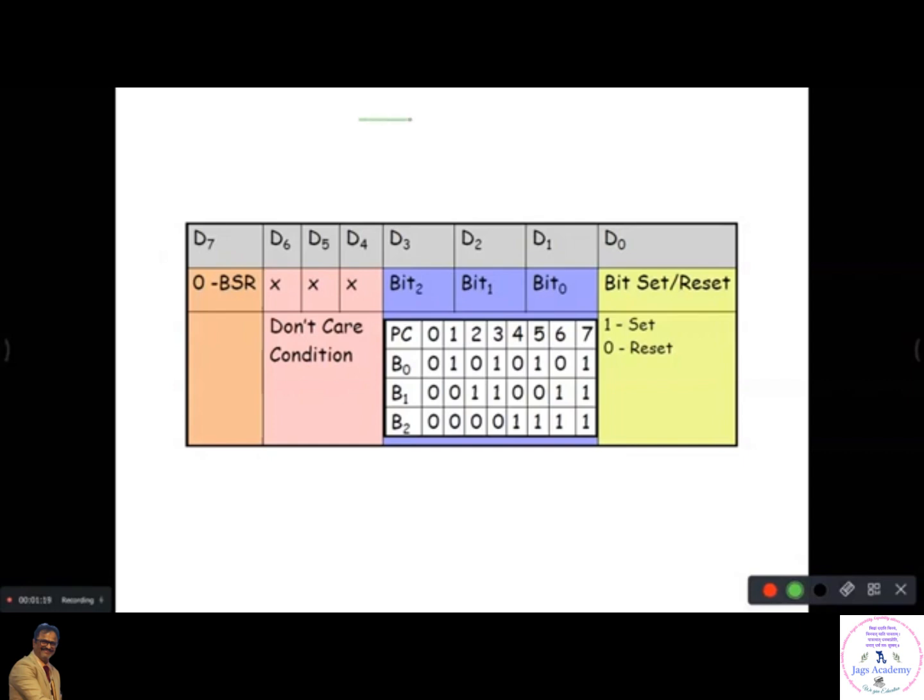First I will draw your 8 lines. 1, 2, 3, 4, 5, 6, 7, 8. This is your PC0, PC1, PC2, up to PC7. Totally it is your port C. Now, by using only the control word, we use only the control register to make these individual lines on and off. Using the control word only, we'll try to make these 0 and 1. How to do that?